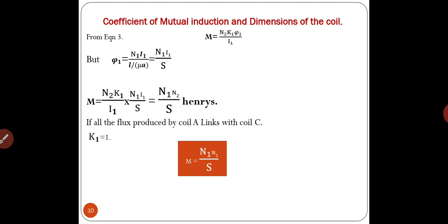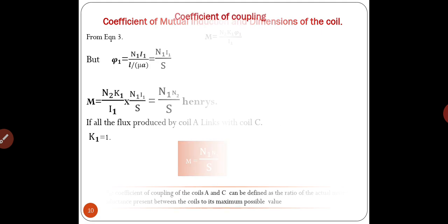And with this we have understood the basics of magnetic circuits. For example, the real applications of magnetic circuits are transformers, which are static devices, and also the DC generator, which is a dynamic device. Dynamically induced EMF is generated in the generator, whereas in a transformer the statically induced EMF is generated. So with this we will conclude the session. Thank you so much.